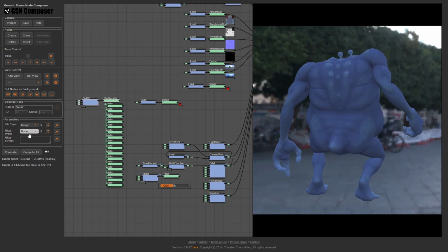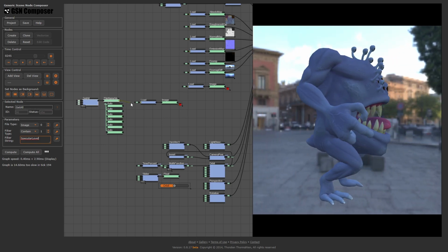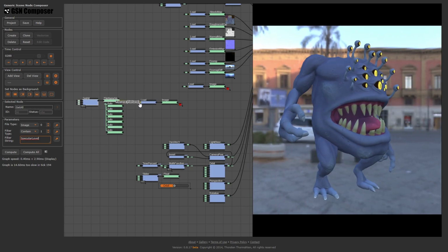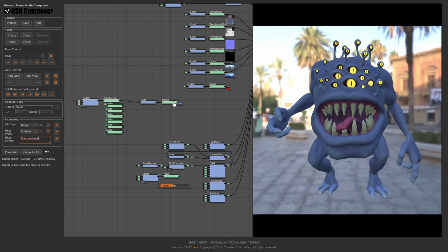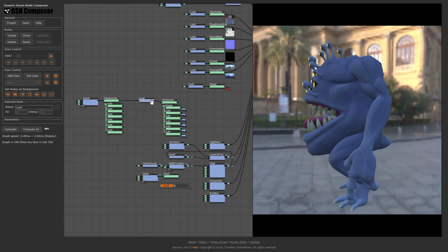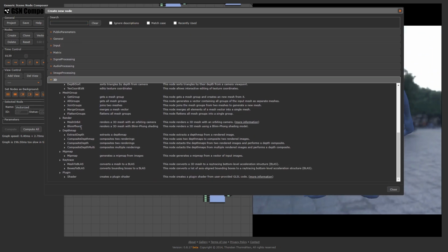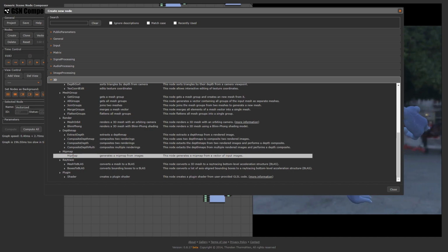Here we can filter the input to contain specular level. We get a vector of 6 file names, which we can pass to a load node. When we vectorize the output, we get a vector of 6 images. We then pass this vector to a node of the type 3D, compute, mipmap, mipmap.